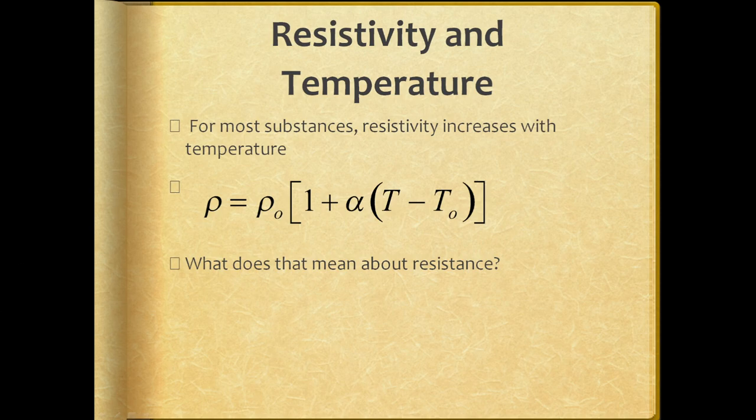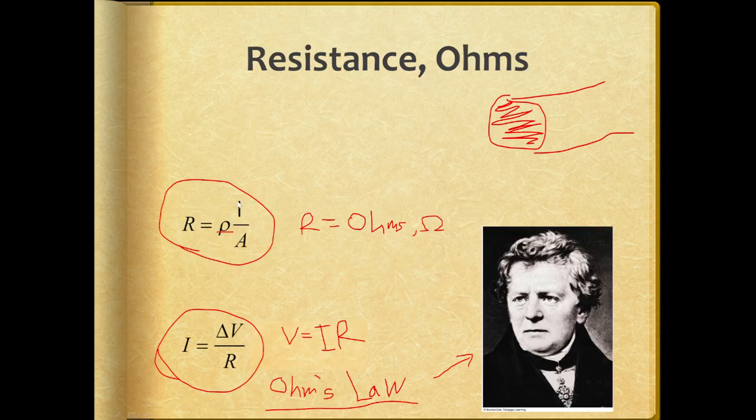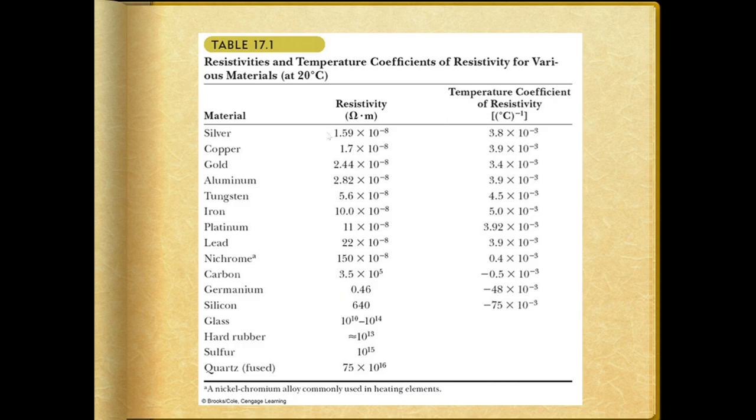So again, I'll tab back to the resistance formula. Resistance equals resistivity constant times object length divided by cross-sectional surface area. The value that you plug into this formula needs to be correct for its current temperature. This column only lists values at 20 degrees because that's kind of the standard.